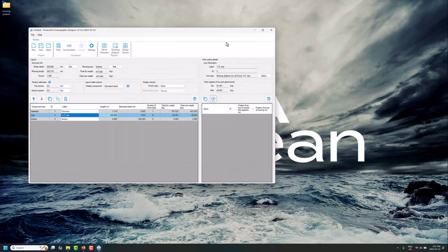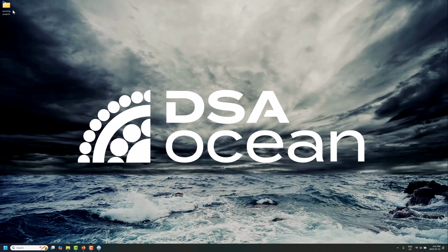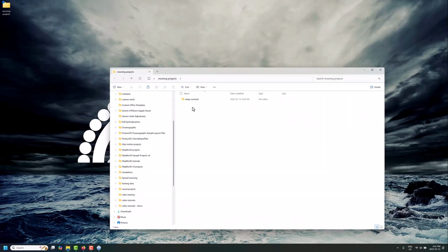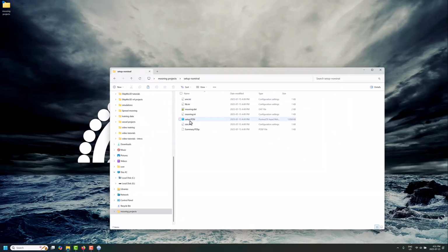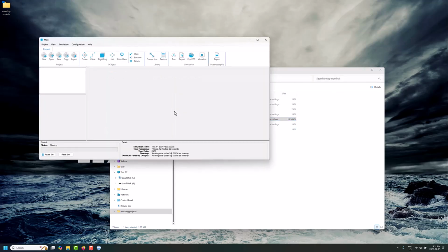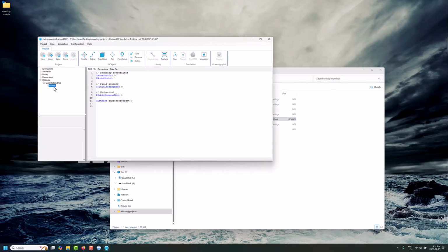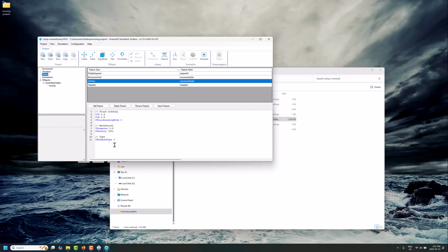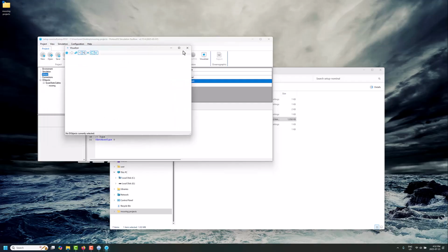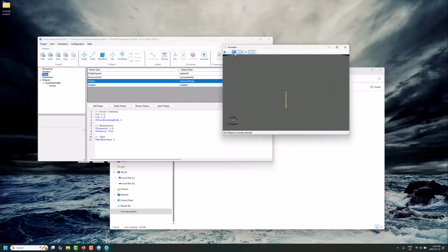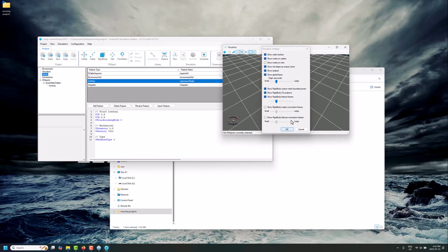Nevertheless, you can do a lot, and it might be in some ways easier to look at directly setting up an analysis in Simulation Toolbox. So what I've got here is a very basic mooring. It just has a line, and we have a little depressor weight on the end. You have to think a little bit, again, upside down, with the anchor at the water surface, and there's more than one way to set this up, but I've followed a similar pattern to what we've shown previously.